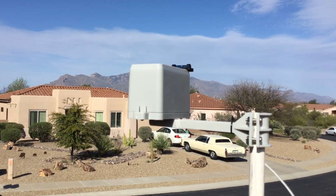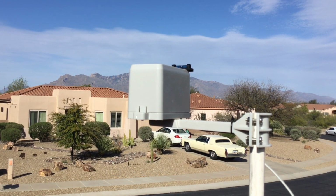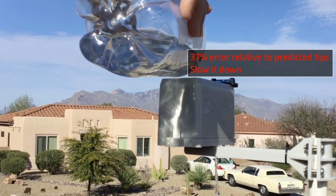Check the video. I lost count while I was doing that, and see how many counts we had, or how many tips. So for this particular test, I realized a 37% error relative to predicted tips. I did try this several times over and confirmed that the issue probably is that I'm overwhelming the tipping bucket gauge given the high flow rate, so I'm going to need to slow things down a bit.